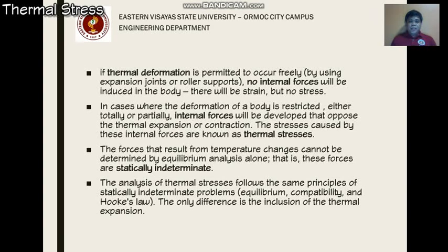If thermal deformation is permitted to occur freely by using expansion joints or roller supports, no internal forces will be induced in the body. There will be strain but no stress. So there will be deformation, but actually the member is stress-free. In cases where the deformation of a body is restricted, either totally or partially, internal forces will be developed that oppose the thermal expansion or contraction.